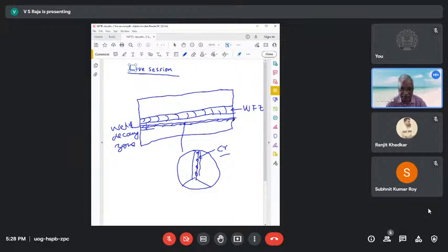The corrosion of this would depend on the thermal cycles. Like, for example, what is the temperature? What is the time taken here? What temperature has this zone reached? How long did this zone remain at that particular temperature? So it essentially depends upon the temperature experienced by this zone due to welding, and the composition of this zone.